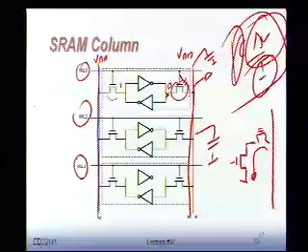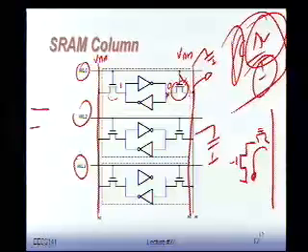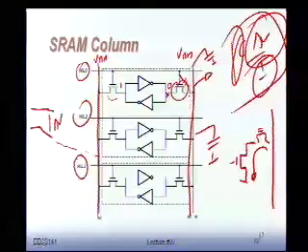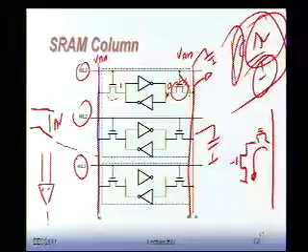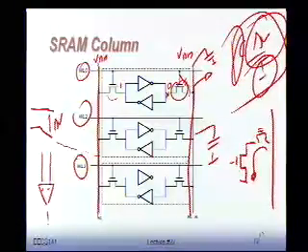We say, okay, we have bit line 1 is high. The other bit line starts to discharge, like this. So rather than wait for this thing to go all the way down to 0, say, no, if I have a delta V which is large enough to detect, I'm happy. I know it's a 1 or a 0. So what we do is you take your two bit lines and you feed them to a differential amplifier called a sense amplifier. You take the small difference, and after a certain time you say, okay, let's turn the amplifier on, and you amplify that small difference till you get it back to the rails.